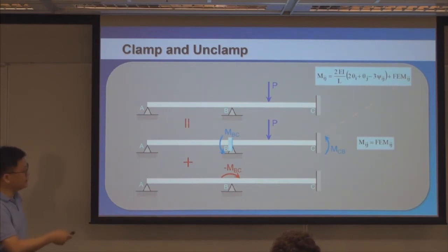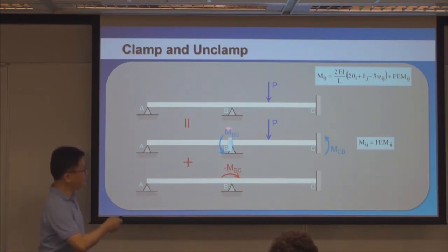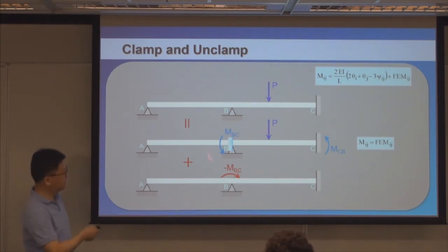And this case is simply following slope deflections. And in this particular case, it's just following the lookup table. All right, so for that nature, we call this fixed end moment. So this is a fixed end moment in the moment distribution.